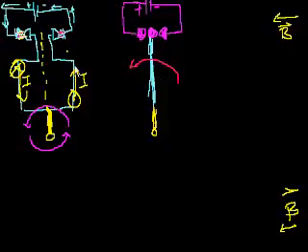kind of, so this side right here, let me do it in a different color so you can see it. This side is this side, right on top, and this side is on bottom, below the page. This side is now above the page, right? If this distance is r, this side is now r units above the page. And I said, ideally, maybe your commutator loses touch with the brushes at this point, right? Because they're popping out a little bit, so when you're vertical, they actually lose touch with the brushes. So you have no circuit flowing, so you save a little battery energy,